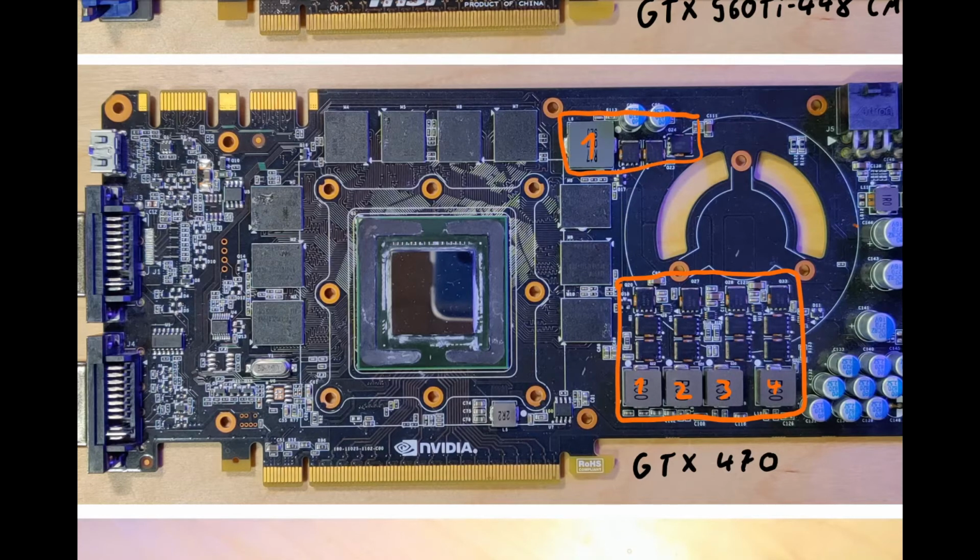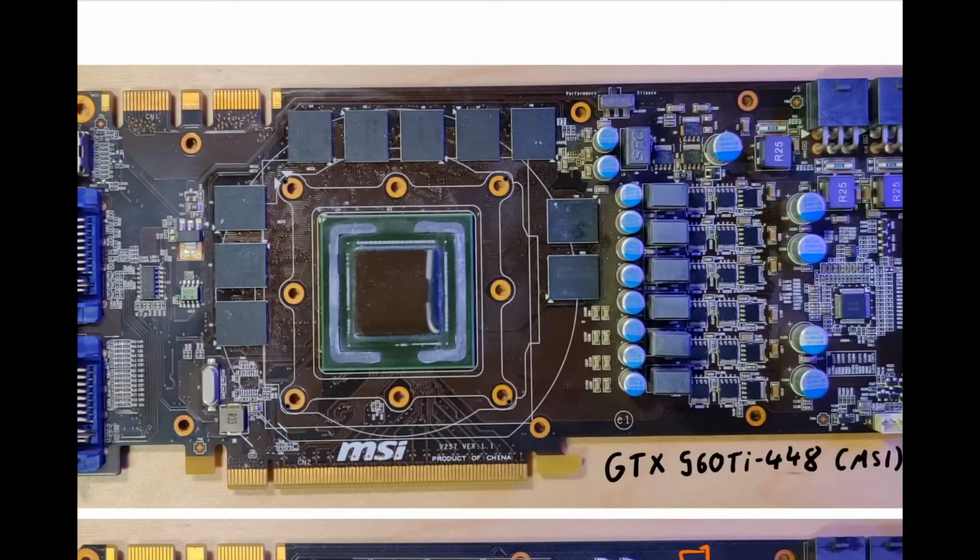Yeah, again, the PWM controller here is on the back. If you look it up, you will see it's a 4-phase, and then somewhere here on the back there's also another PWM controller for VMem. So we'll find that out. Then here we count 1, 2, 3, 4, 5, 6 phases. And here is the PWM controller. If we look this up, we will see that this is also a 6 PWM signal controller, so this is a real 6-phase.